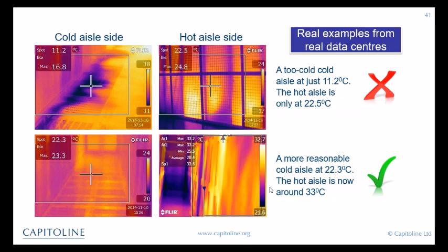At the top here, briefly, you can see it's actually too cold. Many data centers, legacy data centers especially, are run at a temperature much colder than they need to be for modern IT equipment. The one at the bottom is more reasonably set as far as temperature is concerned, and therefore is likely to be more efficient, though use less power for their air conditioning systems. But understanding the limits of where you should set those temperatures is an important criteria that we cover in this training course.